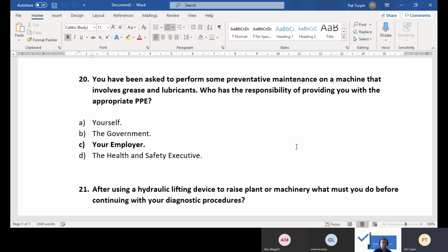What I would say there is, there's nothing wrong with you asking to see or checking a data sheet. The amount of times I've seen someone say, oh yeah, I've got to wear protective gloves, and they come back wearing something porous, like a leather glove or gauntlet, and you think, just check. You need to still know that you've got the right PPE on. So check a data sheet, even if someone said, oh yeah, we've used that all the time.